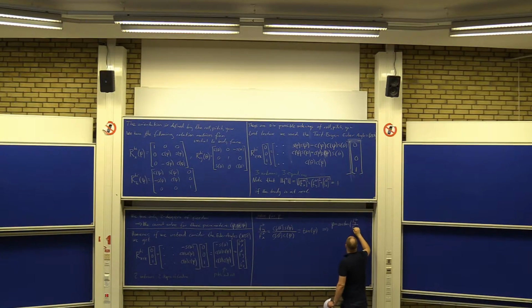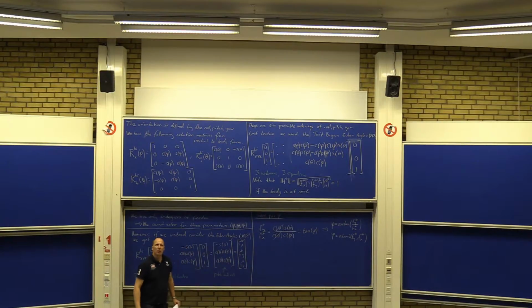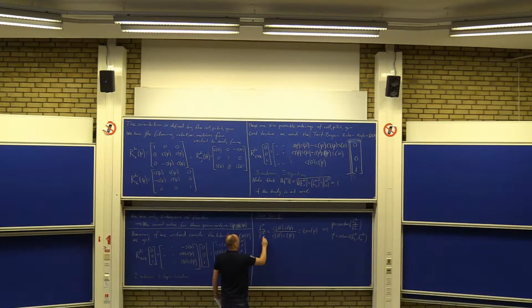f_y^b divided by f_z^b. And for the same reason as we discussed last time, we typically would like to use atan2 instead. So we have the f_y^b here, and then we have the f_z^b here. So we know which quadrant we are in. Yes? Are you sure you mean f_x is the denominator? Yeah, it should be z, of course. y, z, here. Thanks.